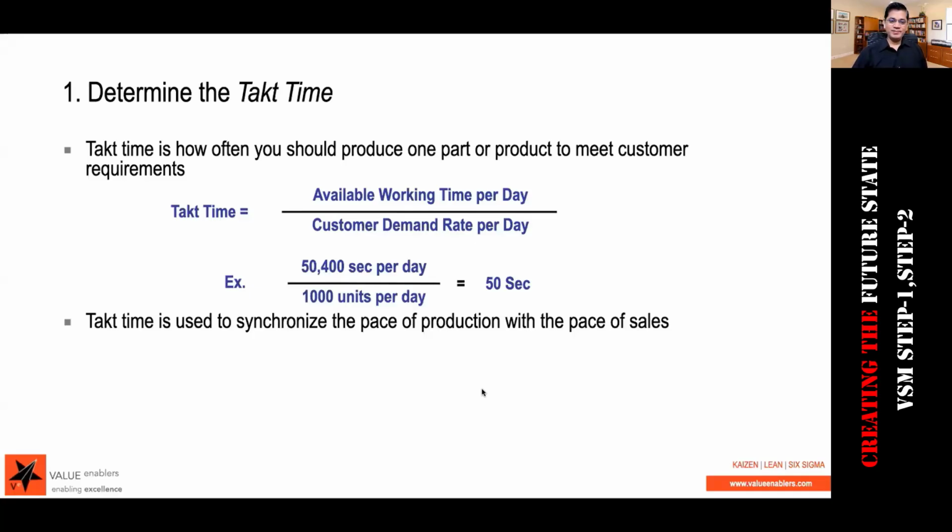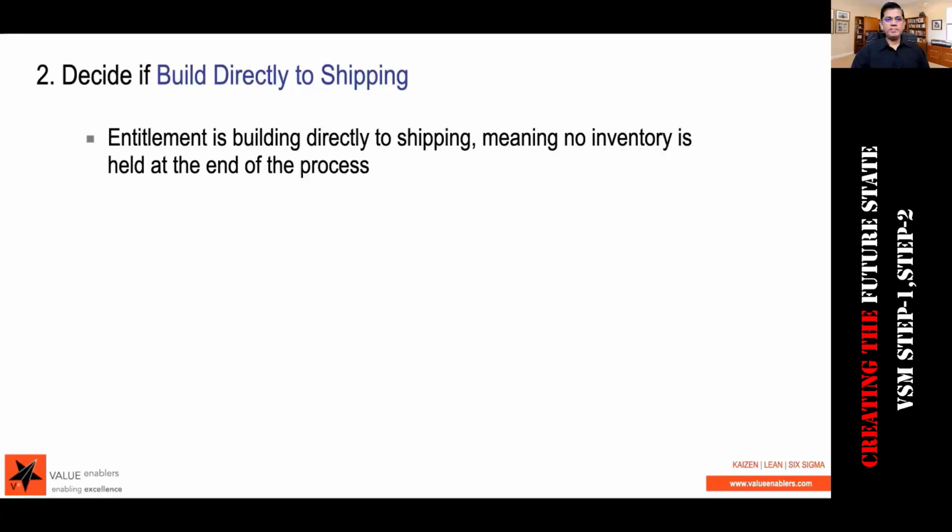If it's a bulb-on moment, sometimes I see something, it's a bulb-on moment, you can type bulb on. Takt time is used to synchronize the pace of production with the pace of sales. We said the process marches with the beat of takt time. Like we say that, okay, 60 pieces in 1 hour, every minute each of these processes should produce 1 piece. Most critical to maintain at the pacemaker step. If it is that critical process, then you can have the pacemaker step.